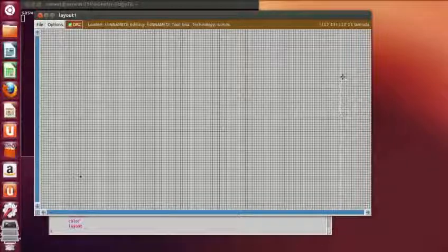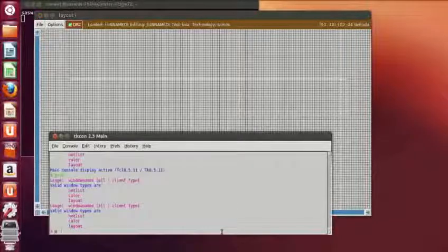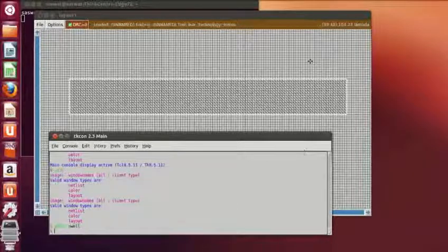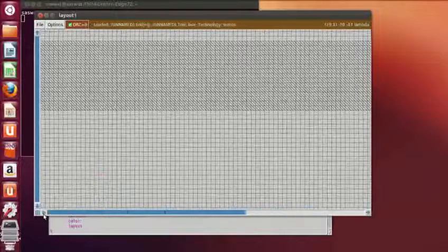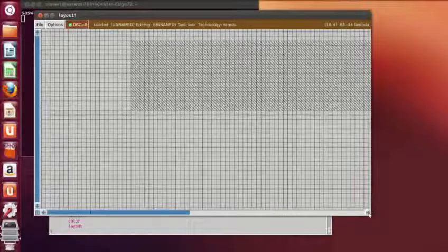So this is the nwell region. Then type paint nwell. Okay. Now after painting this nwell,